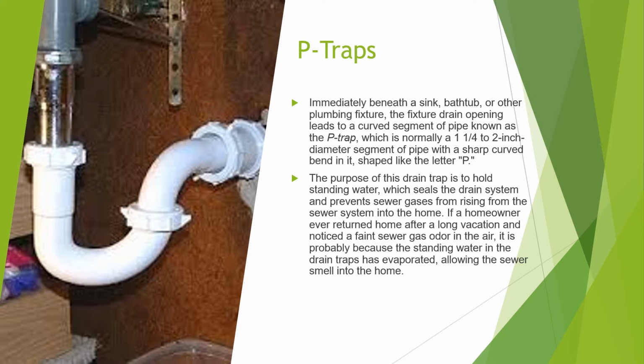If a homeowner ever returned home after a long vacation and noticed a faint sewer gas odor in the air, it's probably because the standing water in the drain traps has evaporated, allowing the sewer smell into the home.